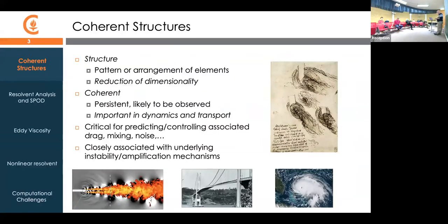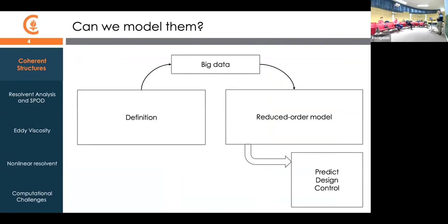So the main topic of my talk is coherent structures and modeling of them. I don't think I really need to explain to this audience what coherent structures are and why they're important. They are, of course, critical in engineering for predicting and controlling things like drag and aerodynamic sound, mixing, you name it. Another interesting feature is that they form a connection between what we understand as instability or amplification mechanisms in laminar base flows and coherent structures that are observed in a fully turbulent regime.